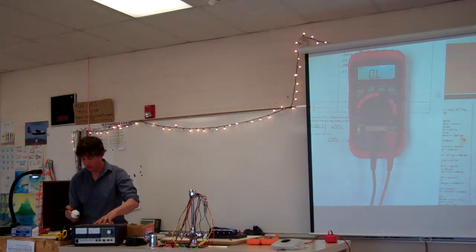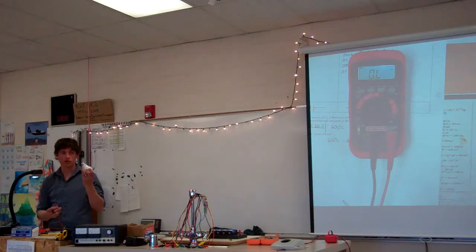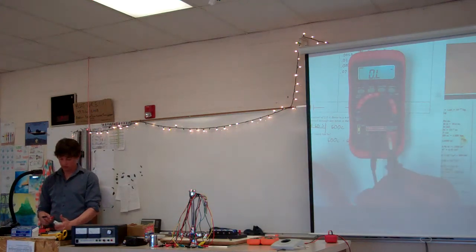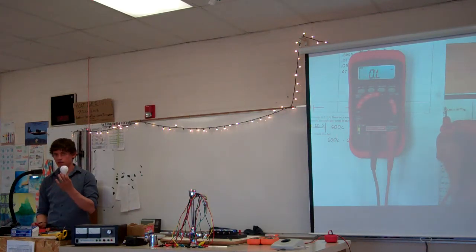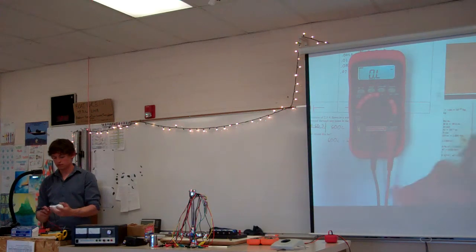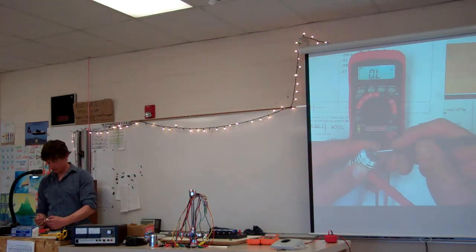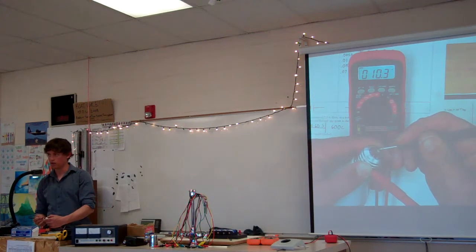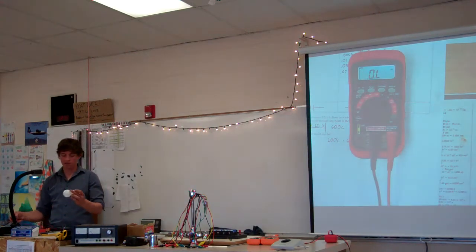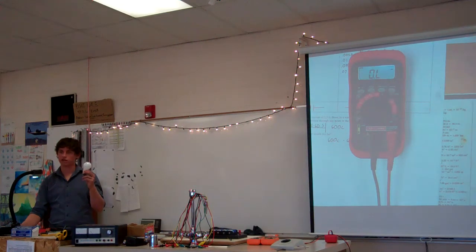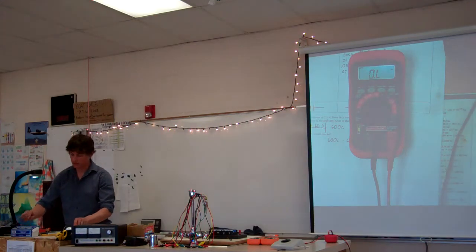Okay, I have another one here. This is a 100-watt bulb. Wait, what was the 40 watt? 29.1. Okay, what do you guys expect to happen when I go from a 40-watt bulb to a 100-watt bulb? Resistance goes down or up? Let's check it out. It goes down. Okay, that one's stabilizing at 10 ohms. So what happens here is this one lets more current flow, doesn't it? So brighter. Yep, it's going to be brighter too.